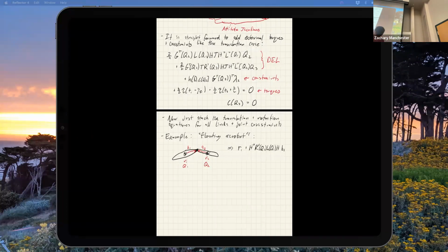So it's literally just this: R1 is in the inertial frame, and this vector is defined in the body frame. I rotated it into the inertial frame and added it on, and that gives me the joint location in the world frame. And now I'm going to do the exact same thing on the other link, so it's R2. I'm going to write down what the constraint looks like. I'm subtracting these from each other and setting that to 0. So everything has a minus sign over here, same deal, just applied to the other link. So this is Q2 and this is A2, and this thing has to equal 0.